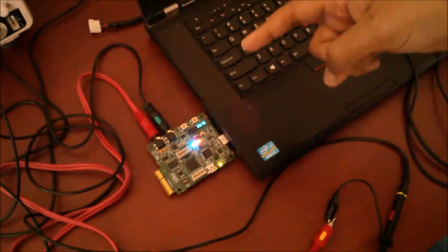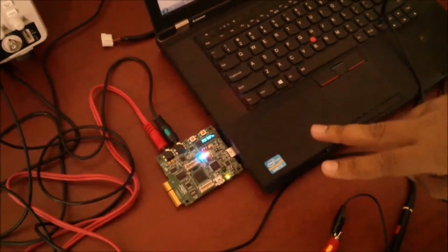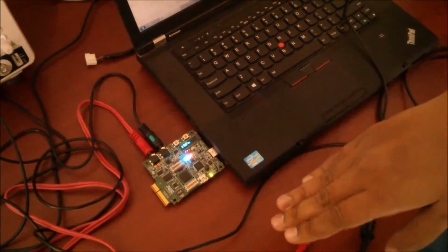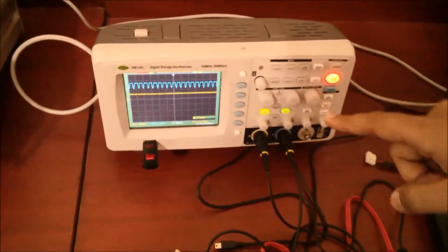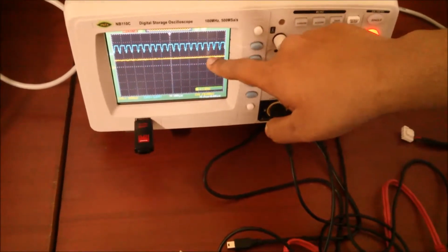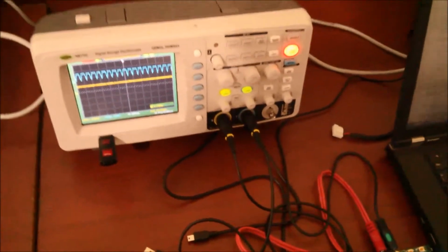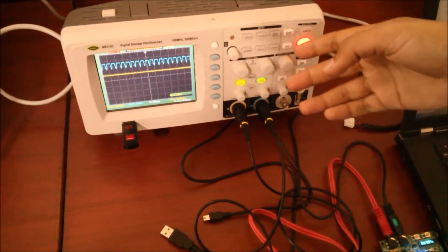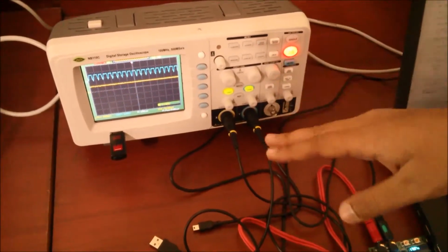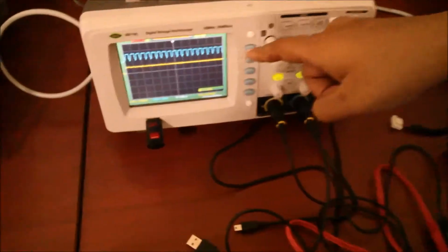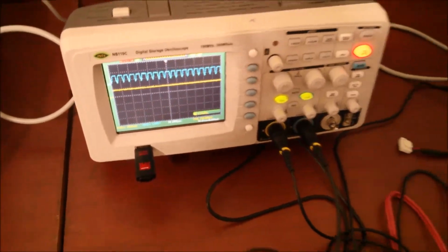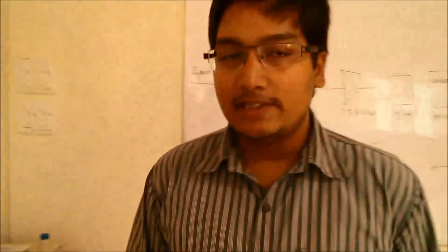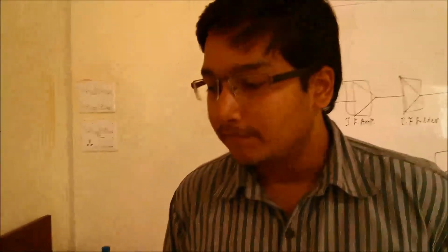Then in the stereo output port there are two channels, left output channel and right output channel. I am using the left output channel to show the final output, that is the DC component that we are receiving here, and the right output channel shows the modulation output which is obtained after getting the product of the reference signal and the input signal. Here you can see it is the blue. So the final output of the lock-in amplifier is a DC component which is observed here.